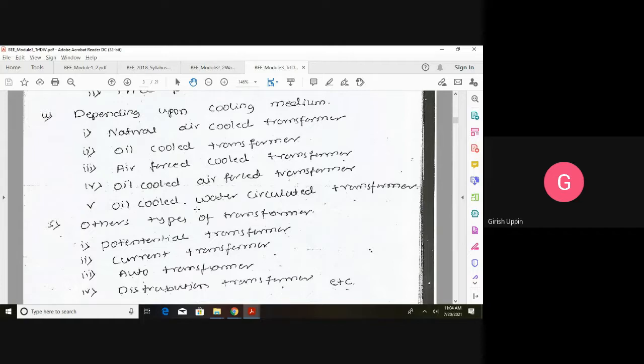Similarly, we have used the magnetic core, and even the magnetic core is experiencing a change in the flux. So we will have loss there also. It is called the core loss. And again, inside the core loss, we have two types: eddy current loss and hysteresis loss. All these losses will be in terms of heat. So heat will get produced depending upon the size of the transformer.